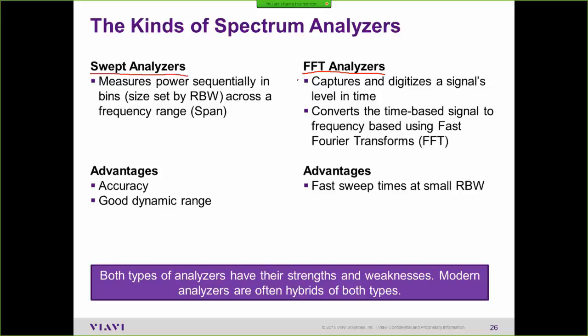And the sweep speed is down, it's 26 milliseconds, even at a very low 1 kilohertz RBW. So for most interference hunting applications, you're probably going to want to run in FFT mode. So sweep mode fast, sticks it in FFT mode, and off you go.